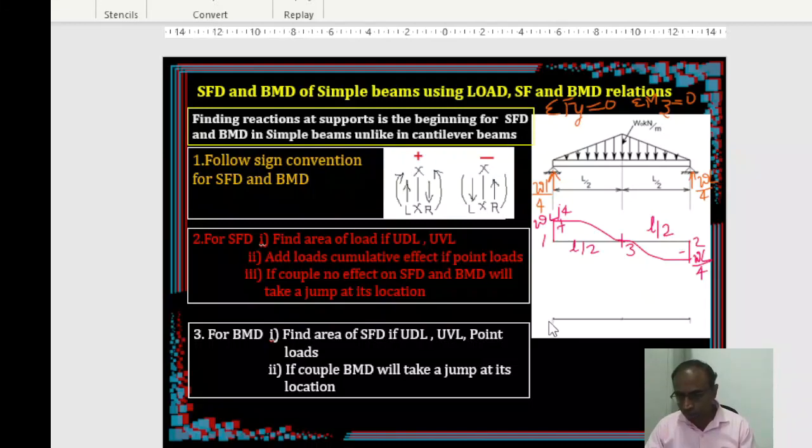Now bending moment diagram is very simple for simply supported beam, because two ordinates you know at point 1, that means at both ends, this one and this one. You see, is there any couple here? As we mentioned earlier, when there are no couples, simple supports always carry 0 moment. So two ordinates you know. So if at middle point you know, your diagram is completed.